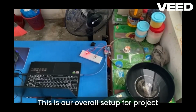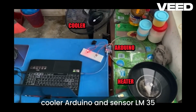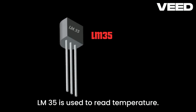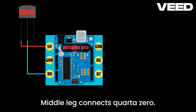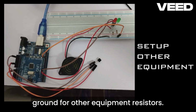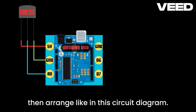This is our overall setup for the temperature control project, which is a heater, cooler, Arduino and LM35 sensor. For the Arduino and equipment setup, the LM35 is used to read temperature. The left leg connects to 5V VCC, the middle leg connects to port A0, and the right leg of the LM35 connects to GND ground. Other equipment like resistors, LED lights and buzzers are set up on the breadboard, then arranged like in this circuit diagram.